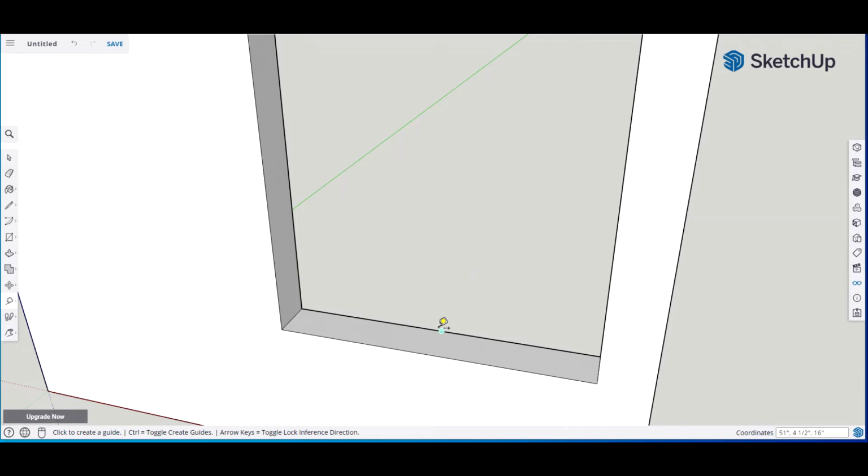T on the midpoint is fine, anywhere is fine, so we're going to go here, 1 space 5/8. Enter. That is better. Now we know that the strip is 1 1/4 inches wide.